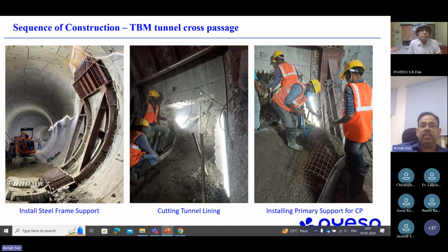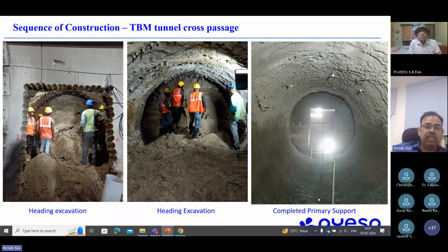So this is for the Kanpur project, Kanpur 05 project. There we applied some grouting in this area. And as soon as we open this and get access, we start installing the heading for this opening. So you can see in the next, we have made some progress in the heading. And here we have made further progress in the heading with the same repetitive cycle. We apply the shotcrete and spiles.